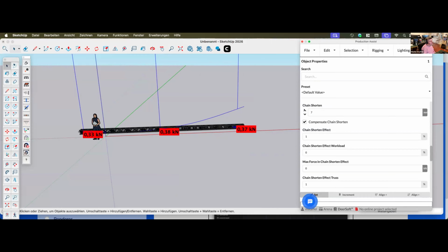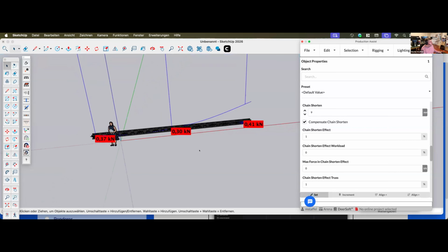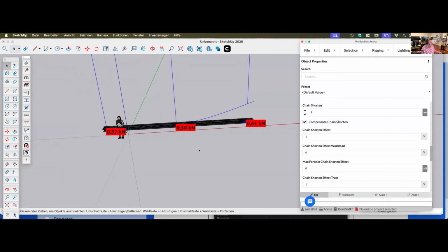And that is basically something that is called leveling with trusses. So if there are more than 2 hoists on a truss run or more than 3 hoists on a frame, then this is a so-called structural indeterminate system, which means that the actual reaction forces on all of these are always based on the right leveling of the structure. So if you hang it a little bit offset, it actually will change the reaction forces of the individual parts. And this is also what is happening on the frames from AluVision, for example.